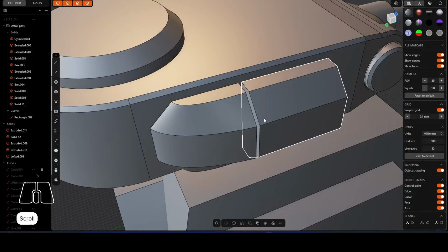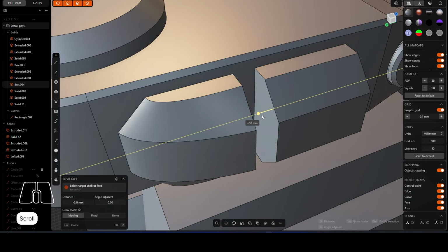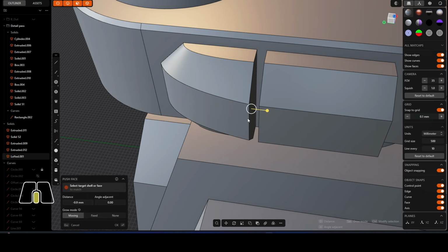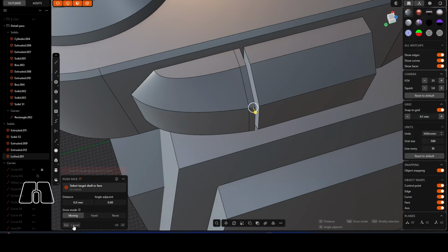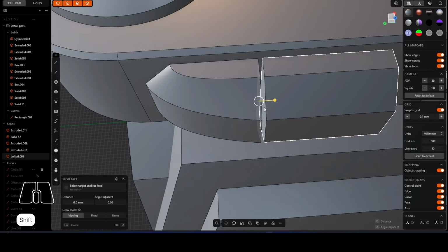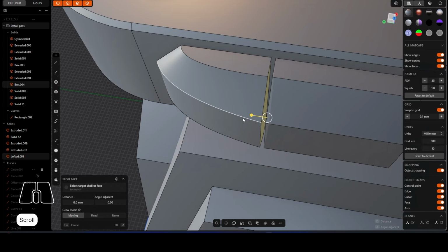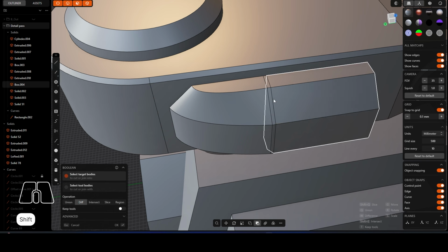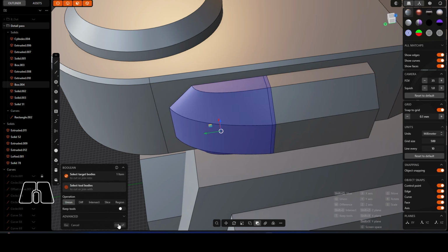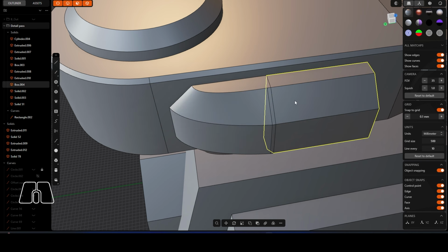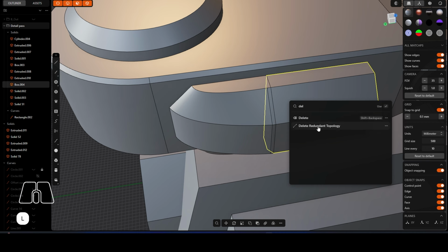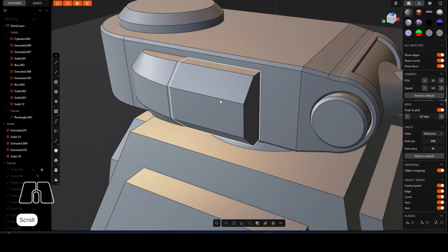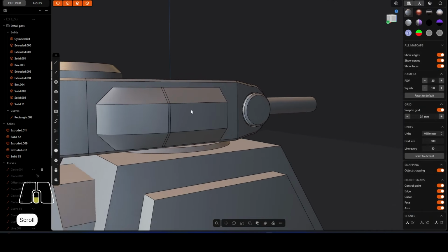So the next thing we need to do is just map this together now. So let's have a look. We should be able to grab this, see if it aligns to the surface. So it's not aligning to the surface there. So what I'll do is maybe I'll give that a loft like so. All right, and then we can use Q and we can union these parts, and then I'll use F and delete redundant topology, and it just kept that line in there for the curve, I think. And then we've got a real nice shape now.